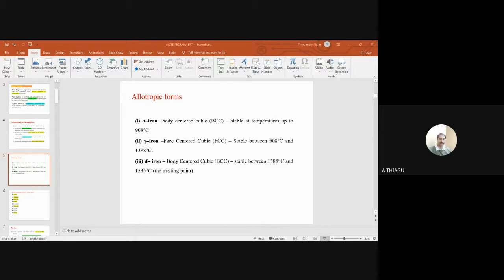Did you get the point? So once again I repeat the explanation. This is the point where the samples are heated at 750 degrees. At this temperature, the entire microstructure is in the form of austenite, and the symbol will be gamma. Then the samples are allowed to cool below 700 degrees. What will happen? The entire austenite is transformed to alpha and cementite. The mixture of alpha and cementite is called pearlite. So this is the appearance for eutectoid steels.